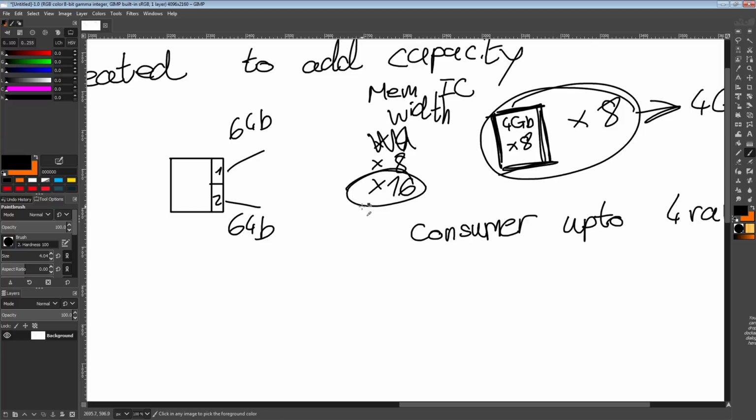And so with X16 chips, that would be 4 chips. With X8 chips, that would be 8 chips. Now, X16 you will occasionally find on very low-end memory because sometimes it just happens to be the cheapest stuff on the factory floor that day, and they'll make a bunch of desktop DIMMs with X16. But generally, if you're buying good, higher-priced desktop memory sticks, they're going to be using X8 chips because that's just normally what you use for the higher end memory sticks.